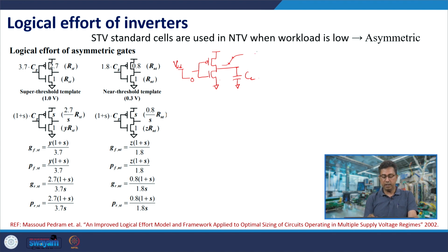Had this been an RC network with RST of the PMOSFET, keep the same CL here. For this rise time, if you give a step input, if the voltage rises from 0 to VDD as a step, how much would be the rise time? For this rise time to be there, what is the value of RST? So RST for the same TR which you get from simulations, that is the RST value that you are fixing for the transistor, RST of P.